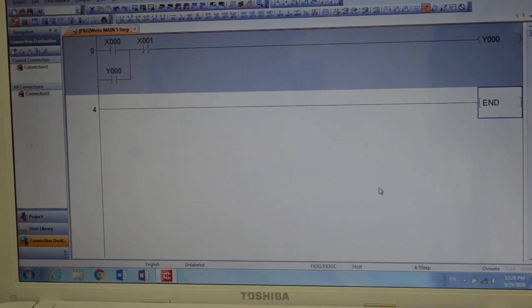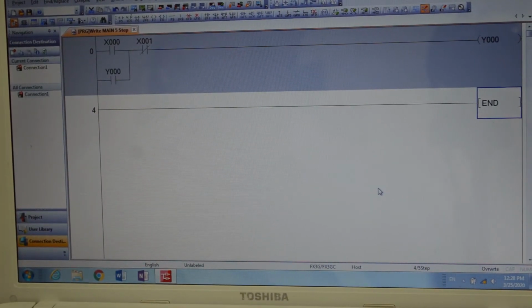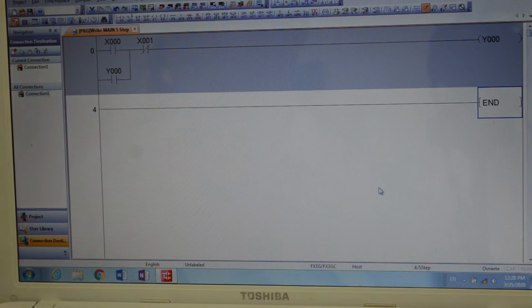Once again, we are here for another lesson in our control technology. This is a continuation of our introduction in the PLC programming we did last time. Our topic for today is the way on how to check and simulate the new program in PLC. This activity will guide you on how to check and simulate the operation of a new program using a Mitsubishi PLC unit model FX3G or FX2N. We assume that the GXWorks application and the PLC program is already open.